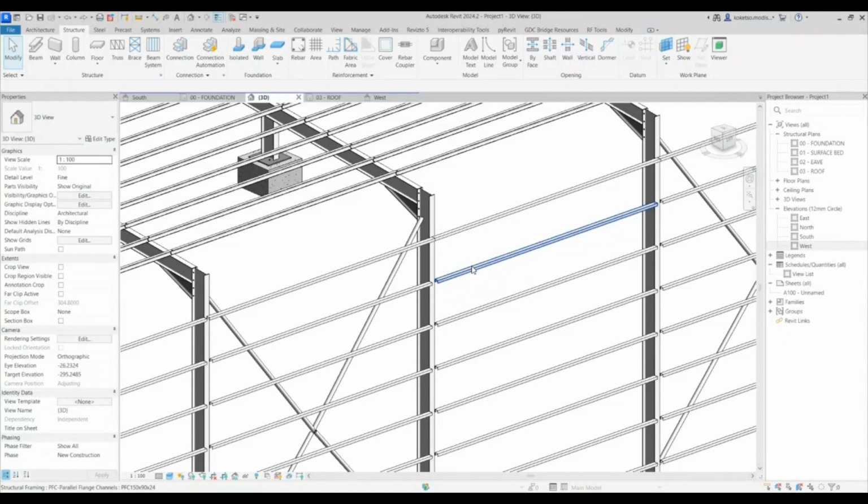So it finished placing those connections. Now we can move on to the purlins. So you're going to go with connection and you're going to select the three of these. And when you drop down, you're going to type in vertical. So you're going to choose this one, vertical tertiary plate, press enter. And then it's going to apply that connection there. So you're going to select this, right click, propagate connection, and those connections are going to be applied everywhere else.